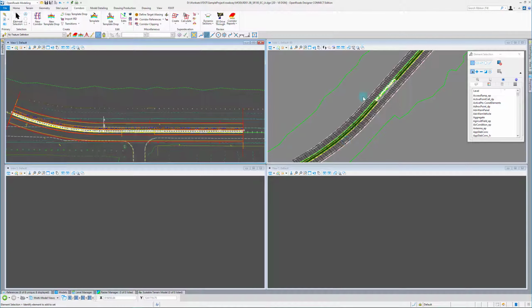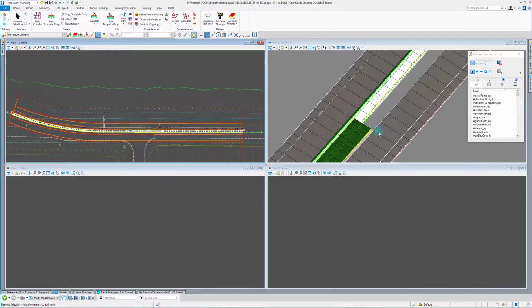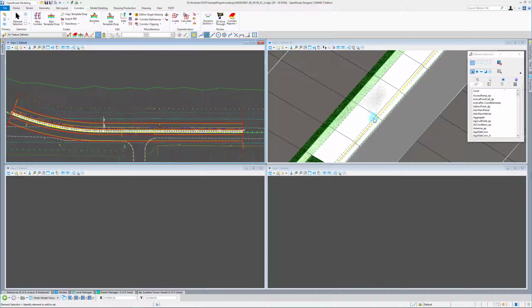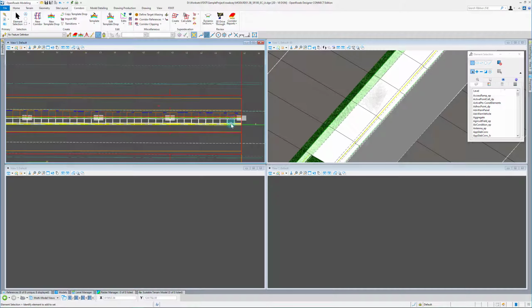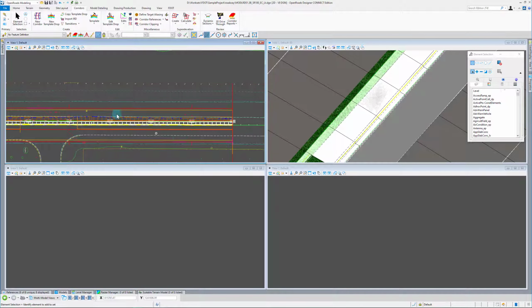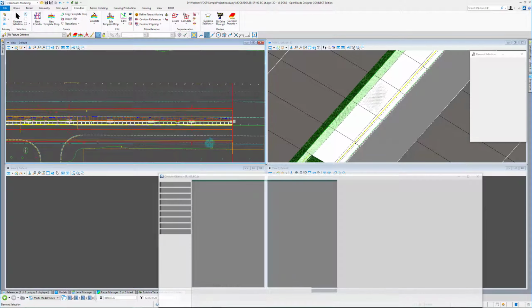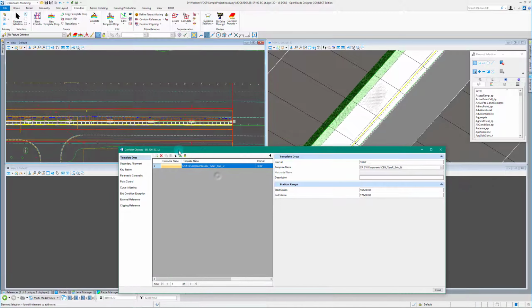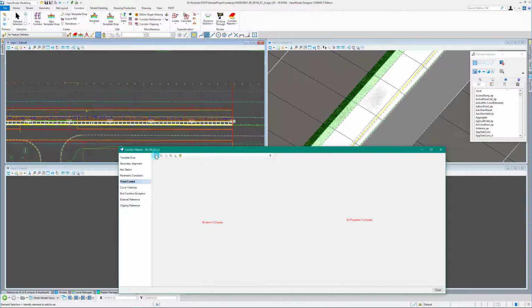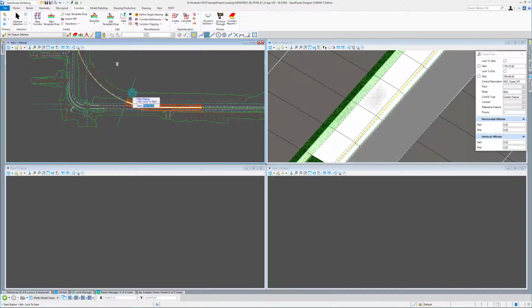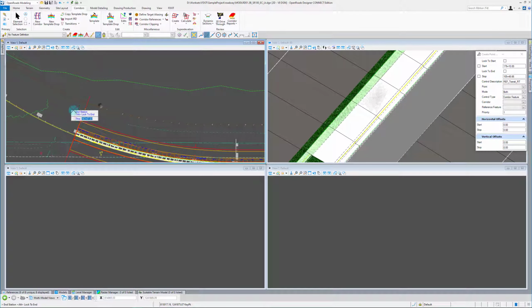And you can see we haven't drawn anything. Well, we have. It's just sitting here because that ref point is running along the center line. So we need to fix that. So what we're going to do is grab our bucket again. We're going to go into our corridor objects, and we're going to create a point control. We're going to snap our point control to our limits again.